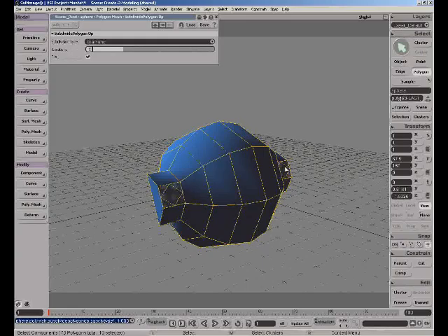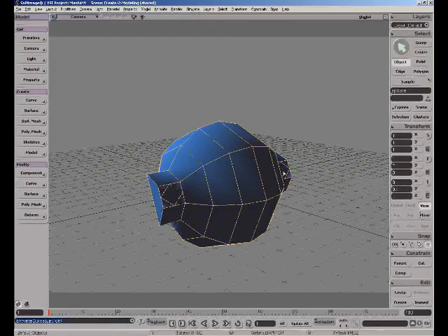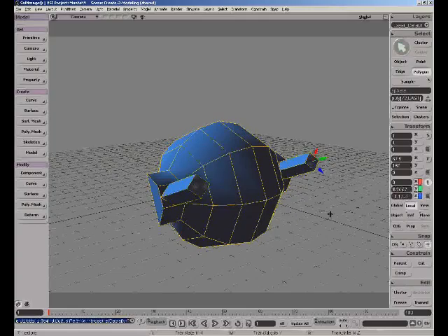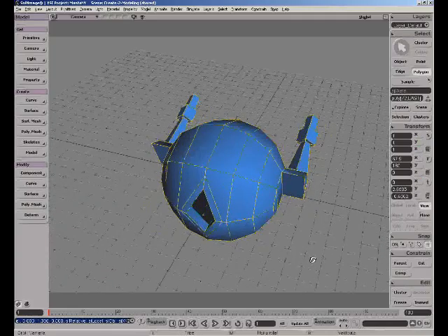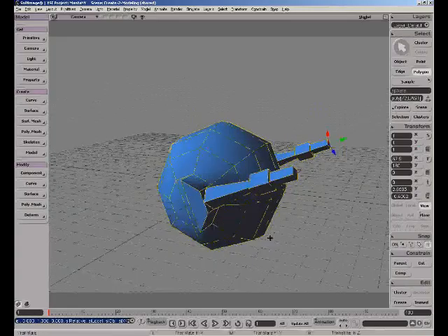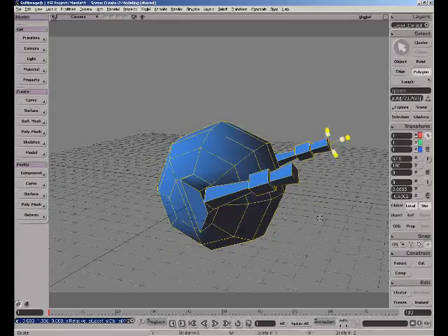So we'll keep this in the diamond setting, and go ahead, select this polygon face, select this one, duplicate those, translate them out like so, maybe scale them down a bit. We can duplicate those, we can scale them up, we can duplicate those, pull them out, duplicate them again, we scale them down a bit, duplicate that, pull them out. You can see it's very easy to just go ahead, extrude polygons, duplicate them. Maybe we'll scale these guys up as well and duplicate them one more time, scale them up like so.